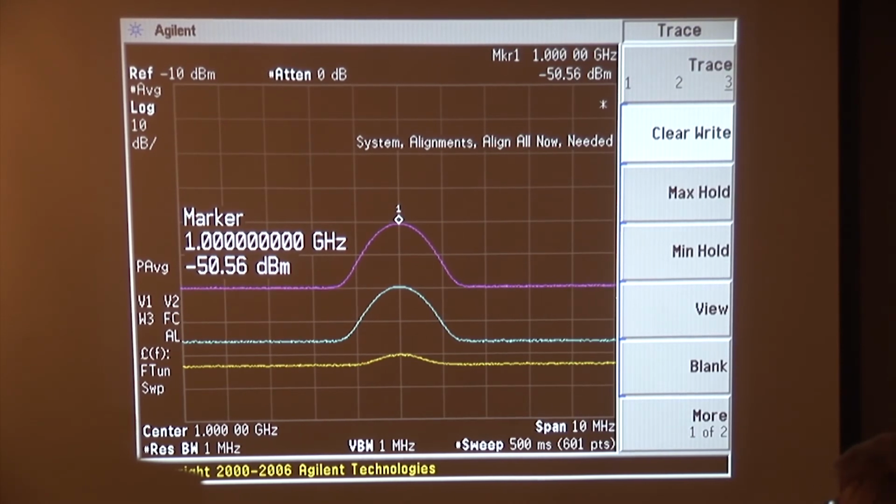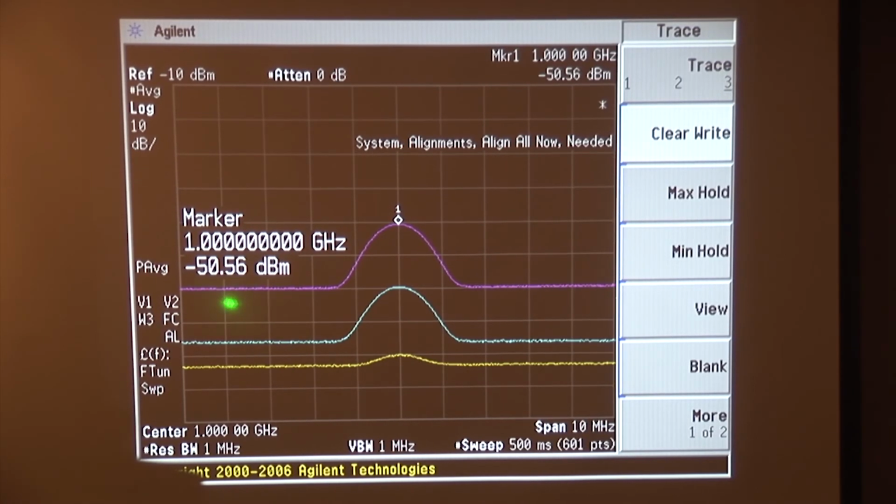Okay. All right, now, what's happened? What's happened is we're looking at the noise floor of the second amplifier right here. Before we had about 16 dB of signal to noise ratio. We now have about 20 dB of signal to noise ratio. There are 2 reasons for that. One is the noise figure of the second amplifier is a bit lower than the noise figure of the first amplifier. Plus, with the additional gain, if we go through the cascaded gain equation, we'll see that we are approaching an overall system noise figure that's a little bit closer to the actual amplifier noise figure.